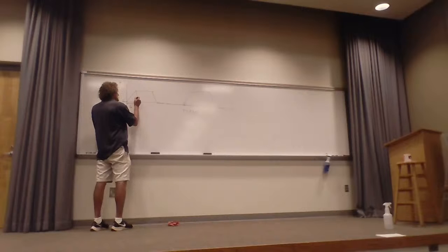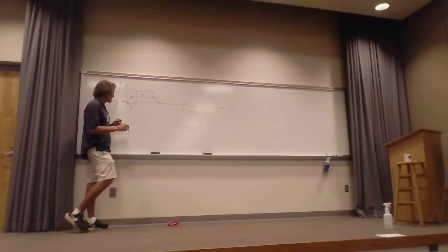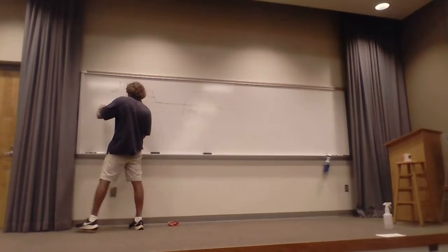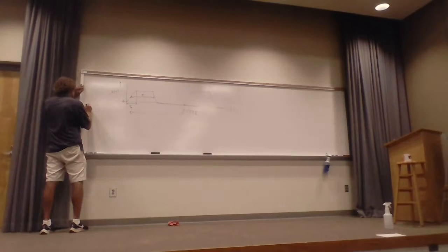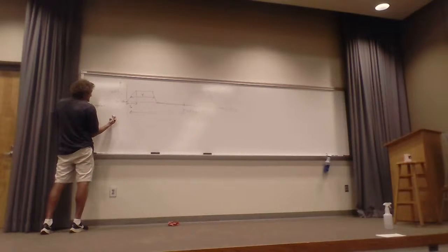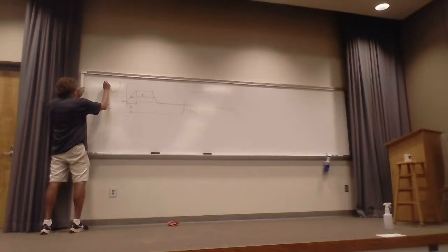The way we do it is the length from this 50% point here, they call this tau, and tau is the on time. And then the period T is here. They talk about something called the duty cycle, which is the percentage of the time the wave is high or on, tau over T. I'm going to refer to tau as the on time.